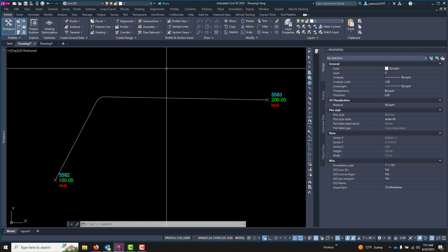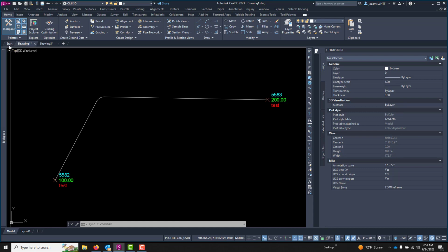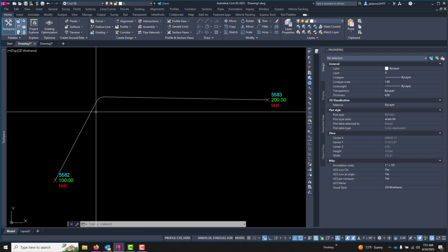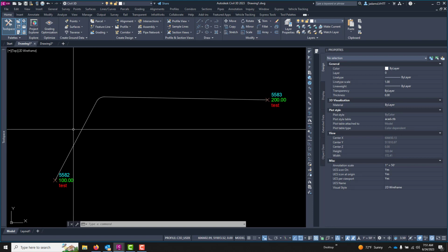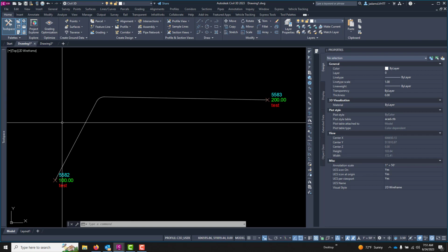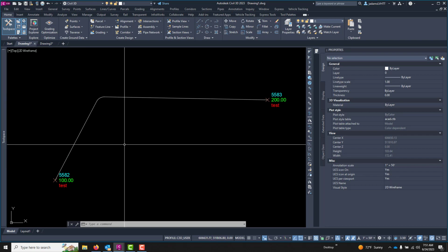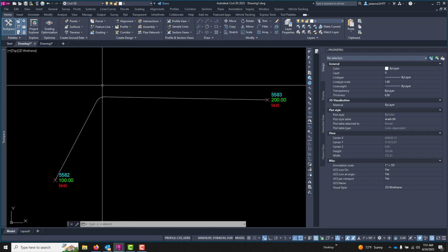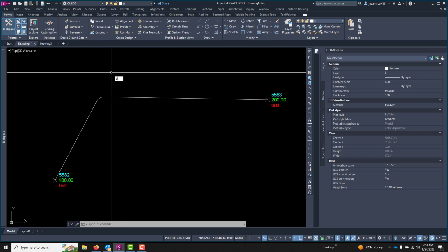Another thing is that Civil 3D out of the box, if you've noticed, when you open the program, it will automatically load the start tab and a Drawing1. So not only is the program booting, opening up all of its ribbons and everything in the background, it is also opening up a drawing and all of its assets, which can take a while depending on your computer. Another variable called STARTUP, you are able to change that behavior.